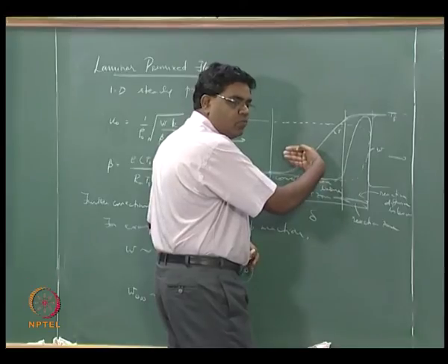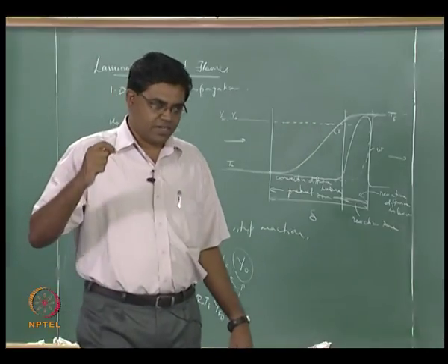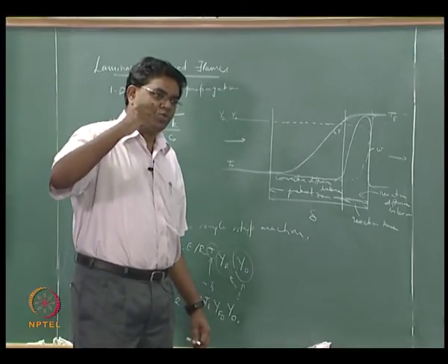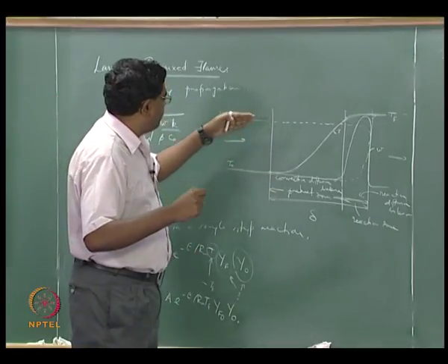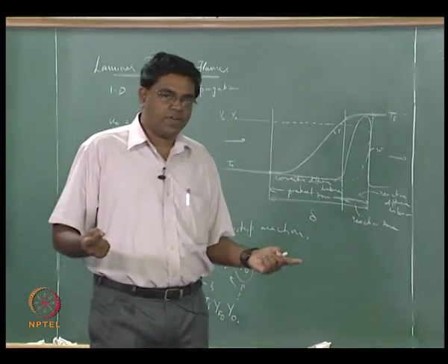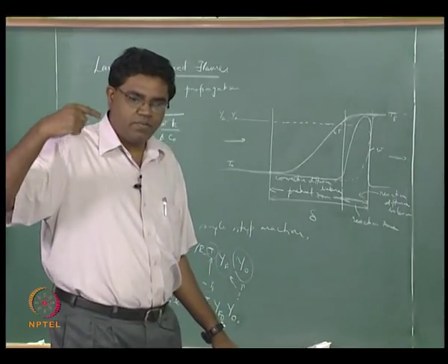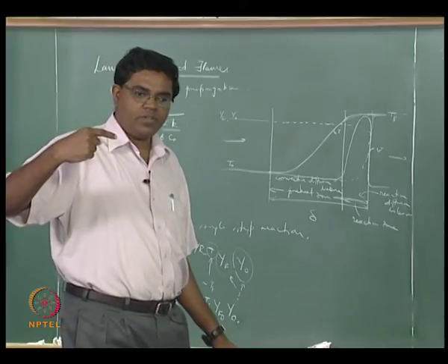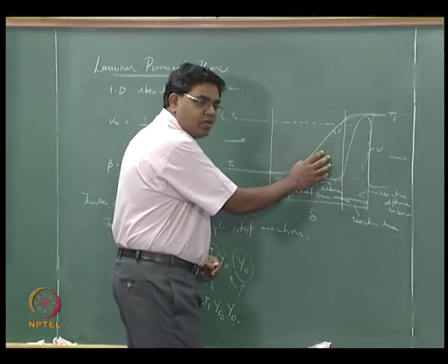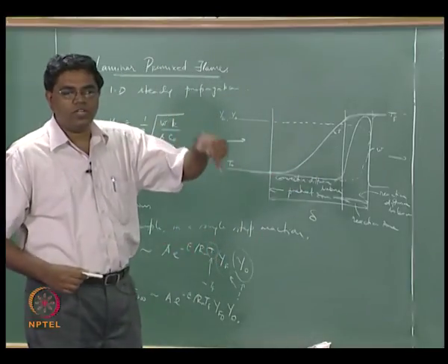Well, if you had product upstream diffusion, what is that saying as far as the reactant concentrations are concerned? Concentration really means how much of what you have is there in relationship with what else is there, right. Mass fractions are all about the density of this species divided by the density of the mixture, right. So that means if you now have products over here, you have other things that are coming in and contaminating your reactants, so the reactant concentrations are going to dip,